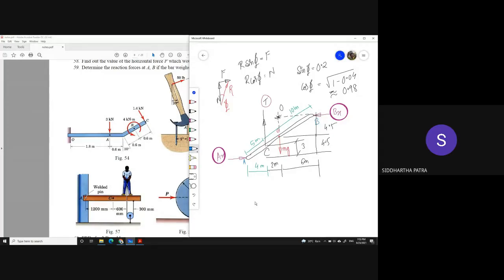Okay, so the normal reactions are the same, right? AX and BX. Yes, sir. And what are their values? 326.67 Newton. Okay. And tension must be equal to mg, right? Yes, sir. So around 1500. Yes, sir, 1470.